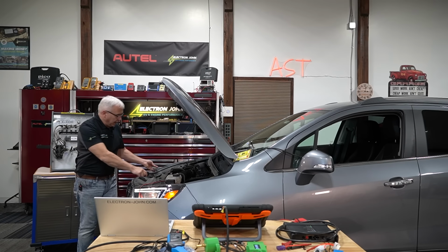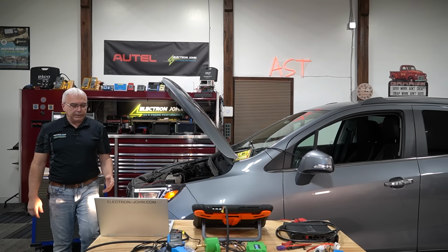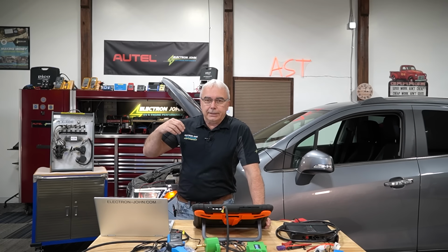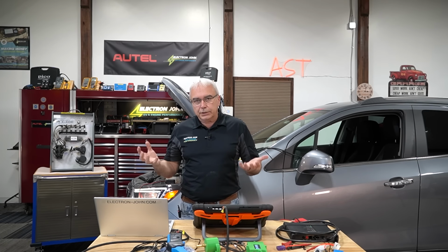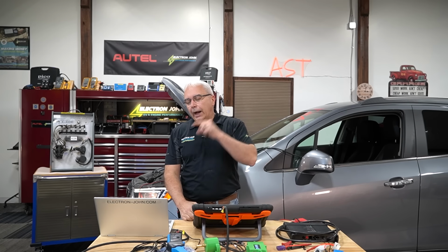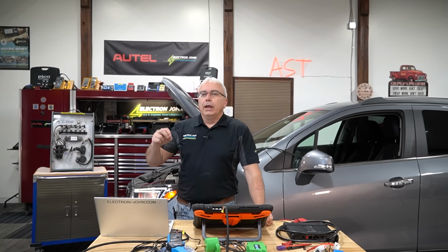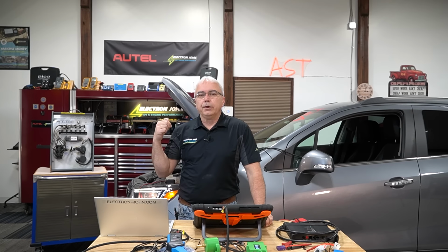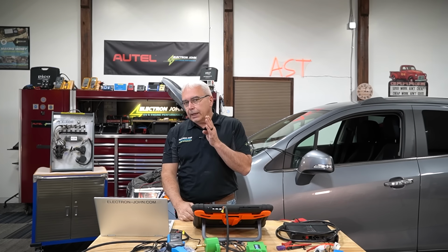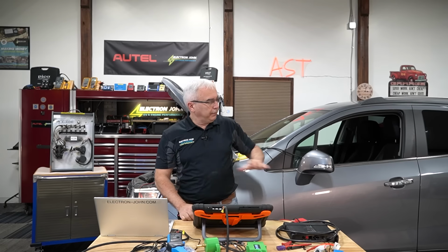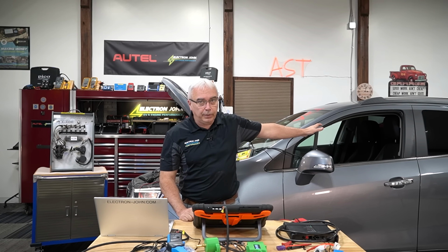so I know which cylinders could possibly be causing the problem. Now, one little word of advice. When we're dealing with exhaust back pressure, it's a tube, right? It's an exhaust pipe. So when I look at my actual waveform coming in the exhaust and I hook up to a firing order here, it takes a little bit of time for that exhaust pulse to make its way from the engine out to the tailpipe.